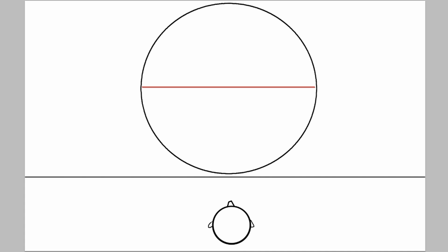And if we take the points where the circle is widest at that center and trace them back to our observer, we get something like this. However, this is clearly not the widest point that the observer sees. If we have a look at where the observer's eye line is tangent to the circle, i.e. where he would stop seeing the circle, it actually occurs down here. You can see that this creates a wider width on the picture plane than the actual center of the circle. Because of this, this line would actually be the long axis of the ellipse, counterintuitively.